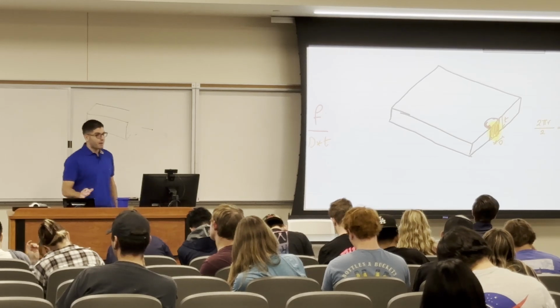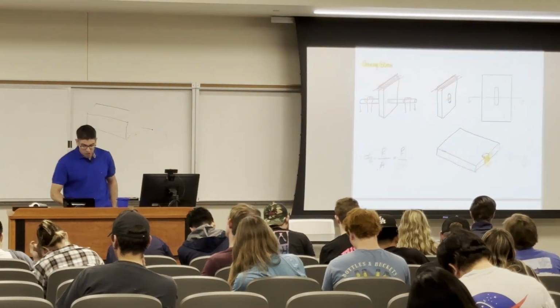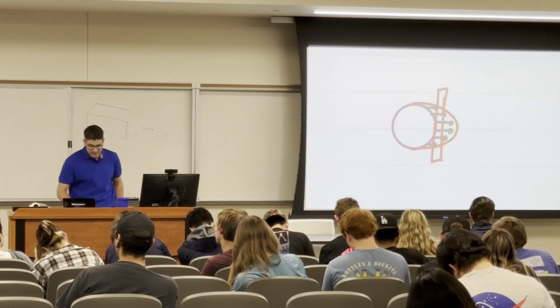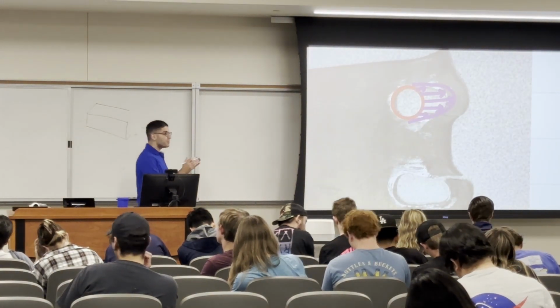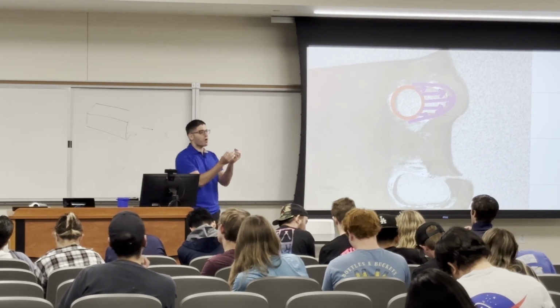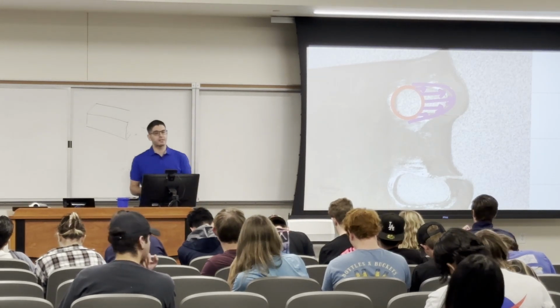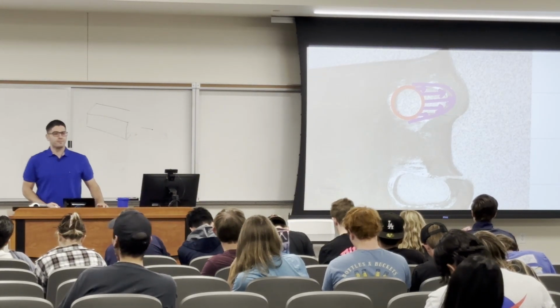And again, I'm not taking any circumference, because the distribution of the stress, as you see from the failure, wasn't constant. It peaked in the middle. So that's why I took a rectangle, like a projected area. Okay? Any questions?